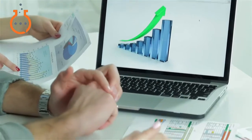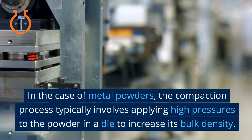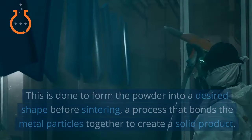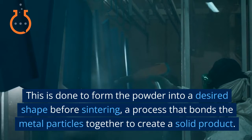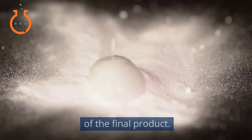Compaction processes. The chemical processes involved in powder compaction depend on the materials being used. In the case of metal powders, the compaction process typically involves applying high pressures to the powder in a die to increase its bulk density. This is done to form the powder into a desired shape before sintering, a process that bonds the metal particles together to create a solid product. The composition of the powder can significantly impact the compaction process and the properties of the final product.